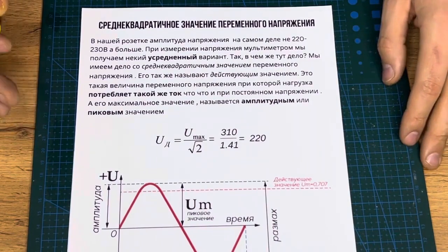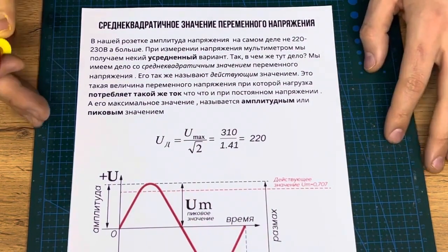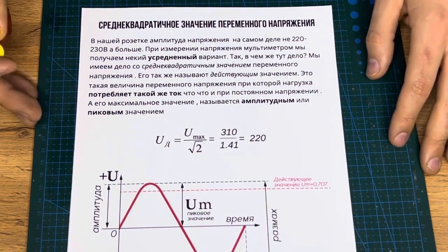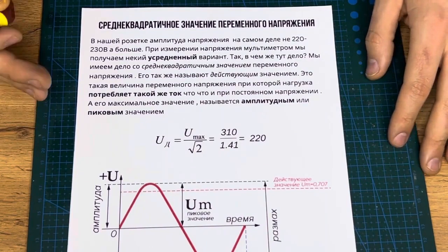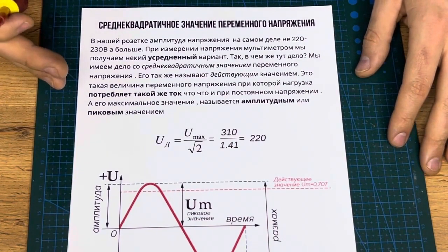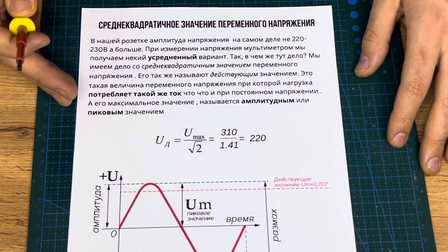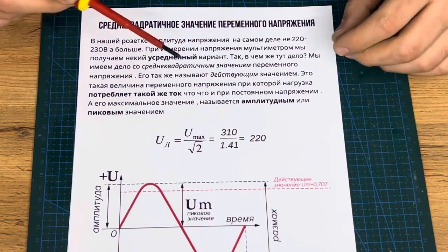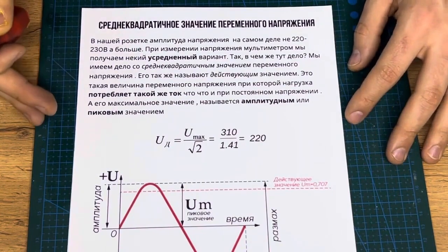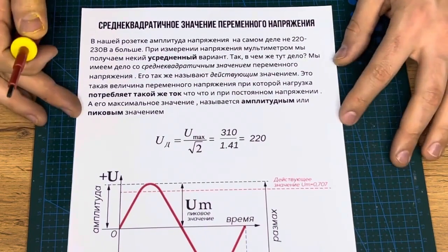When we do diagnostics and measure voltages, I always say that we proceed step by step, right? If we're dealing with a switching power supply, and nowadays most modern devices use switching power supplies, then in any case, we first have an input transient, an input diode bridge. Next, we have exactly this capacitor. And it is on this capacitor that we need to measure the DC voltage, which should be around 310 to 320 volts. So the question is, where does it come from?